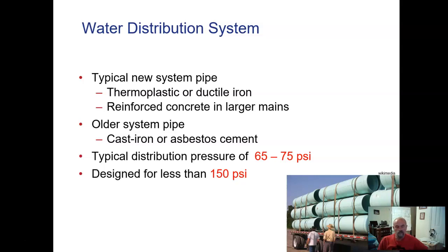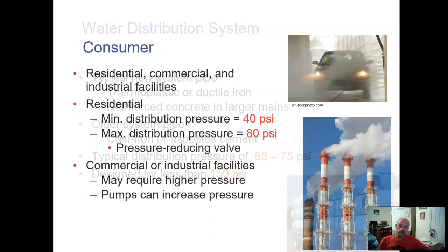A distribution system pressure of 65 to 75 psi is often recommended. Pressures over 150 psi though can cause leaks and damage to the system, so they are pre-regulated before a system to bring it down, if that's the case from booster pumps or high volume pressure systems.